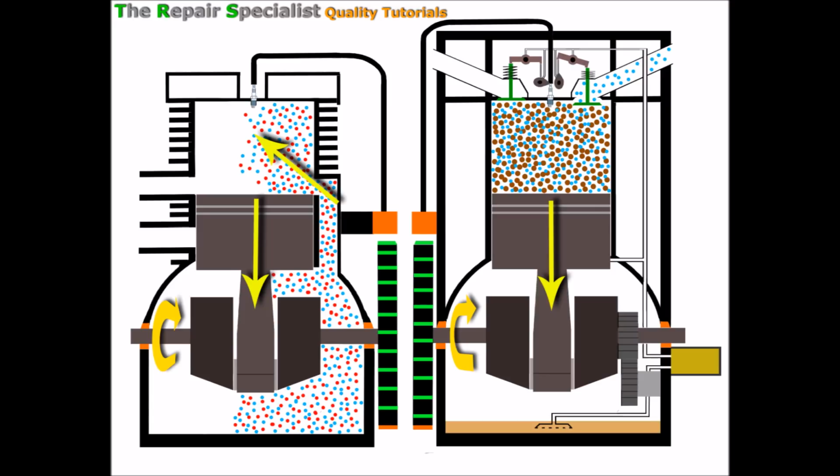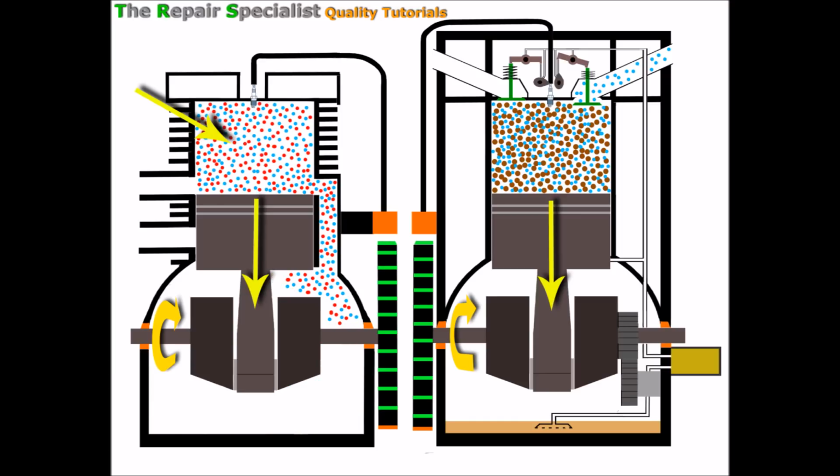And the pressure beneath it continues to push all of that air and fuel into the cylinder area there above the piston. Now, although I've shown that the air and fuel has gone from the crankcase now, in reality there would probably be quite a lot of air and fuel still hanging around in this area. I've just illustrated it this way to show the flow of air and fuel. But as that mix of air and fuel passed through, it lubricated all the components, all the crankshaft, the bearings and the cylinder, because the fuel has with it the two-stroke mix oil. So wherever that fuel-air mixture goes, it's lubricating, and it's doing the same up here, so that when the piston rises, there's going to be lubrication between itself and the cylinder walls.